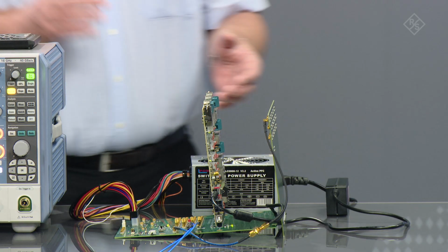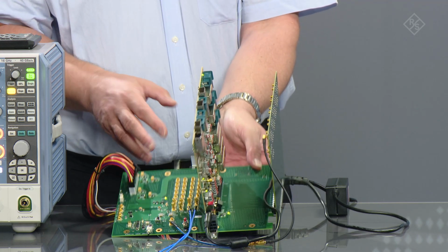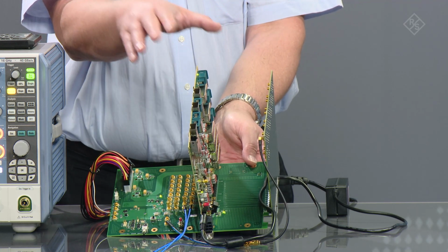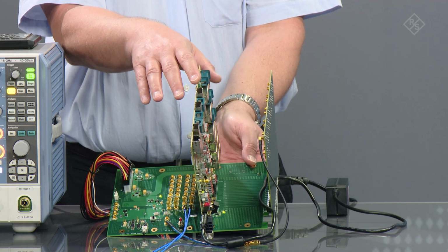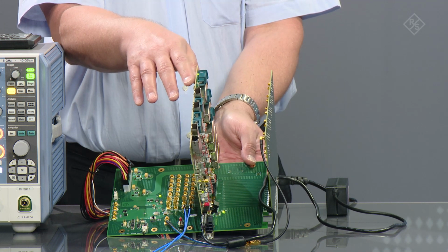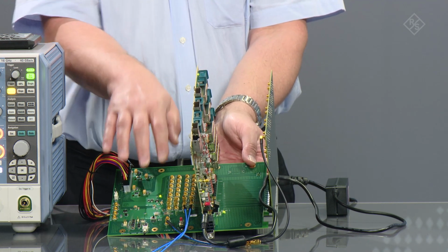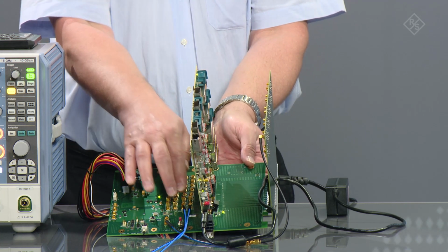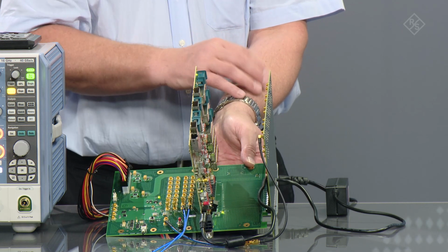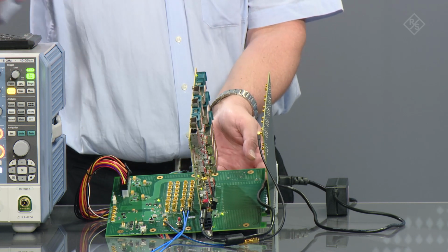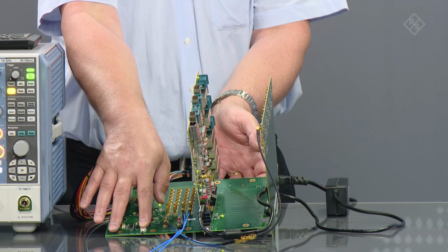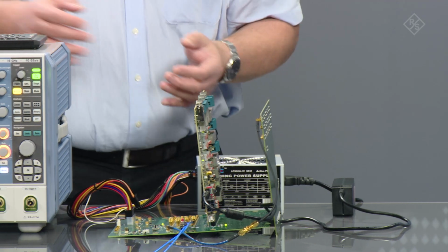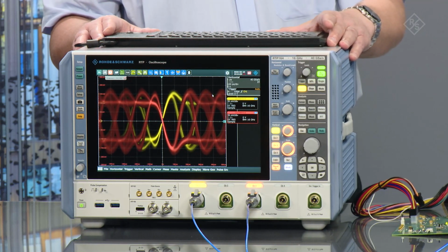We have here a PCI Express Gen 3 compliance baseboard that has the riser card. Then we have the domain controller, the 4 lanes PCI Express connected to the compliance baseboard. We have here 6 termination resistors for 3 lanes. And for lane 0, P and N are terminated by the oscilloscope here. And using the toggle button, we have already selected the preset 0 for the PCI Express compliance.